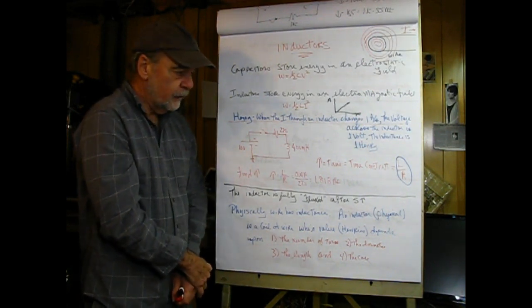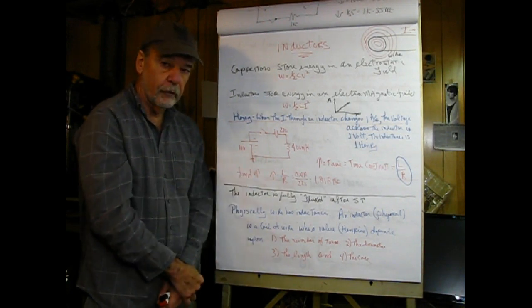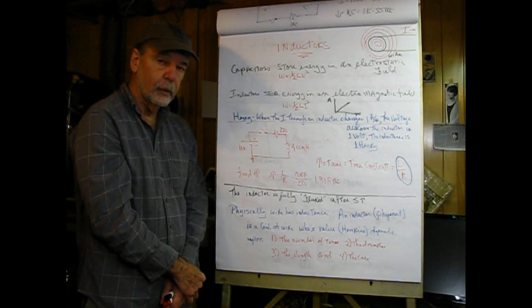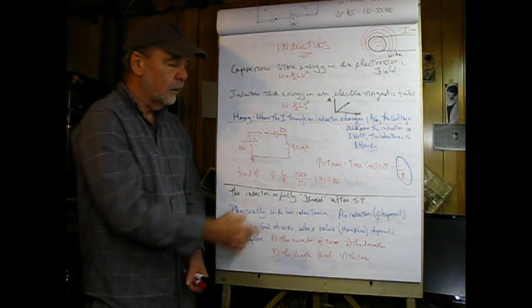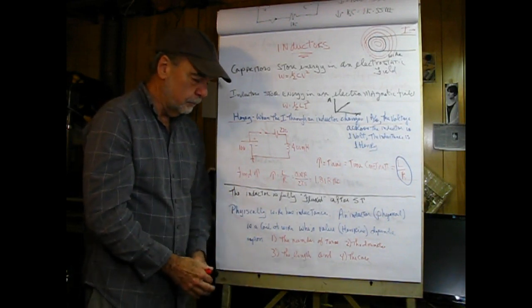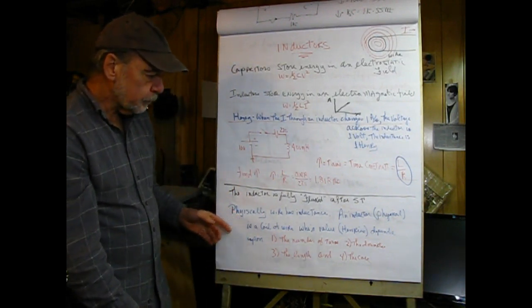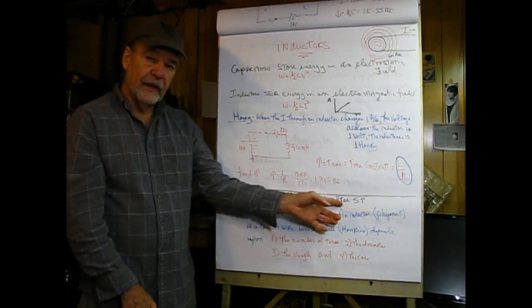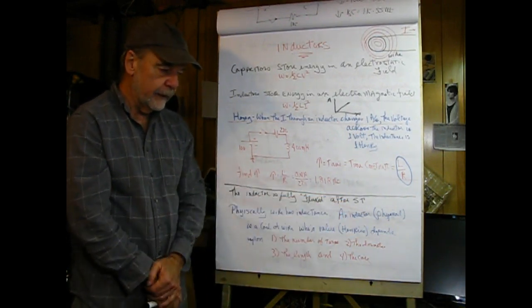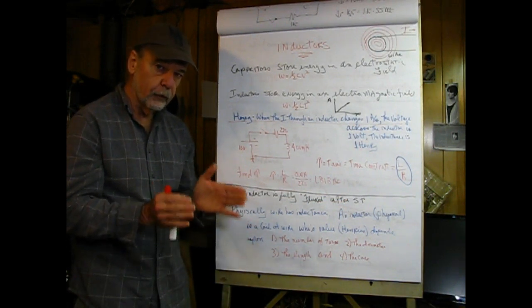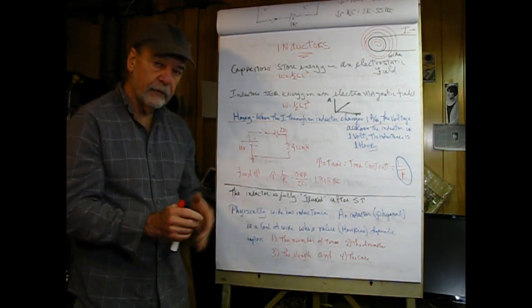In AC circuits, this phenomenon will be referred to as inductive reactance. It's actually a counter EMF, a counter voltage, which is formed in the inductor by the growing of the field. Anyway, the inductor is fully fluxed after 5 tau, just like a capacitor, and that's also asymptotic, but the industry says that it's fully charged after 5 tau.